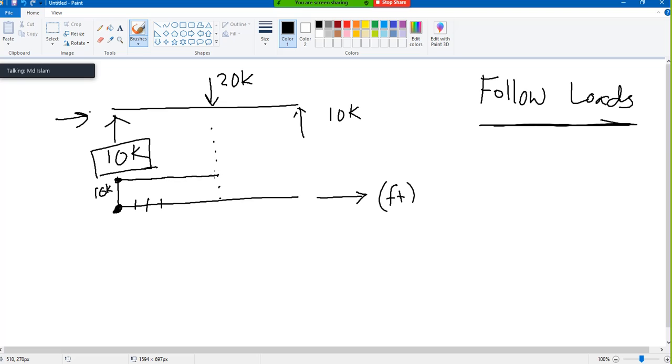After I came here, there is something: 20 kip. Take a new color. Now what is 20 kip telling me? It is telling me 20 kip down. My value here was 10, because we got this 10 from here. Now we go 20 kip down. So 10 down here, another 10 down here. So I will come to minus 10. Hopefully you know where I got minus 10: I had 10 kip minus 20 kip equals minus 10 kip. That is this minus 10.